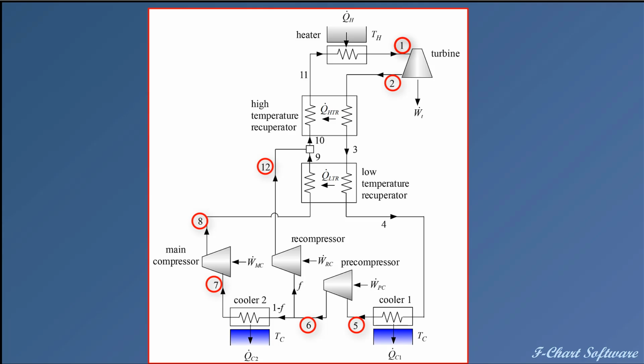So there's probably different ways to do this, but what I'm after here is a way to guess one parameter, and then based on that guess I need to be able to solve the entire rest of the cycle, which would then lead to a single error value that will tell me how far off my guess is, right? As long as I've done that, then the iteration becomes pretty straightforward, and I can ask EES to do that required iteration automatically.